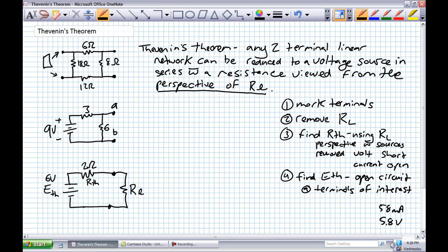Okay, so it's our 9 volts. We're going to add 100 ohm resistance in this fashion. So what we're going to do is go ahead and simplify the circuit. It's a 6 in parallel with a 100 in series with a 3, 9 volt. What is the calculation that we're going to have to do there? That's one calculation.